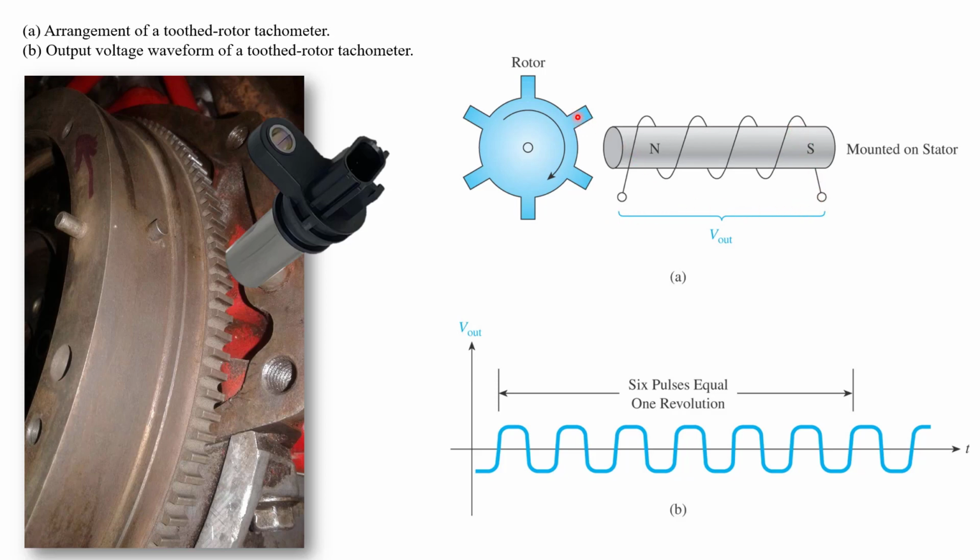But as this piece of metal comes close to this, those lines of flux are drawn toward it, and as those lines of flux move, they're going to cut this conductor and induce a voltage that we can measure. And we'll get an output from this particular device like this. As this approaches, the lines of flux cut and cause the voltage to be induced up.